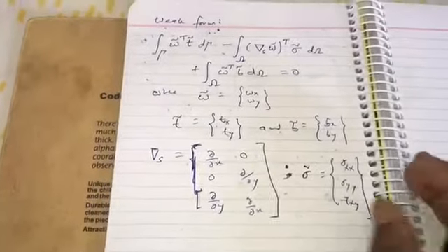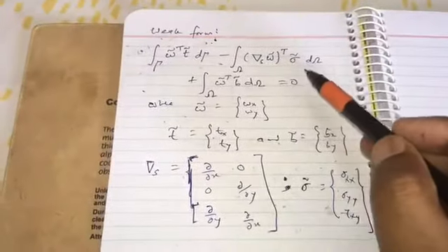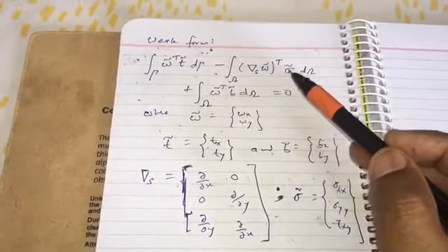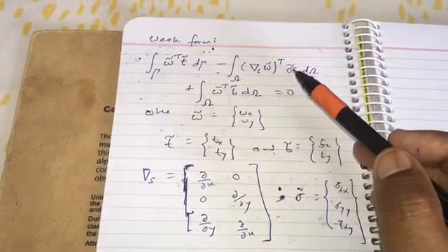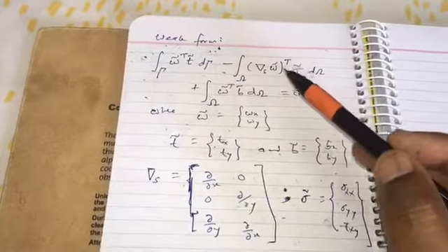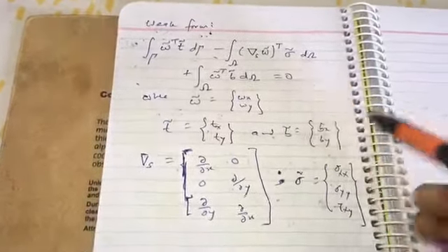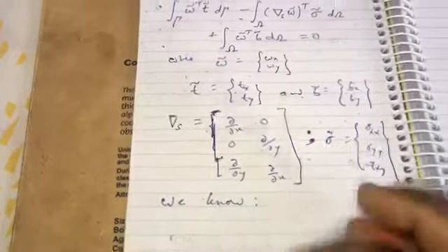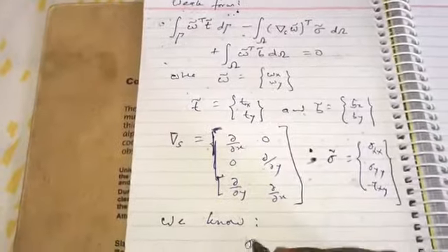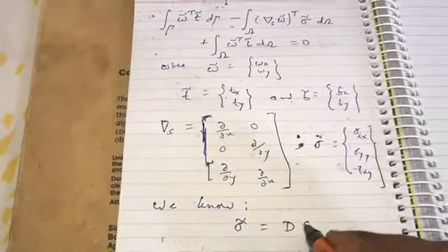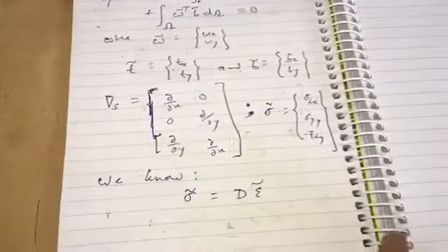Now remember that we also have the relationship between strain and stress, and again the relationship between strain and displacement, that also we can put here. We know already that the stress is a function of strain, where D is the elasticity matrix.